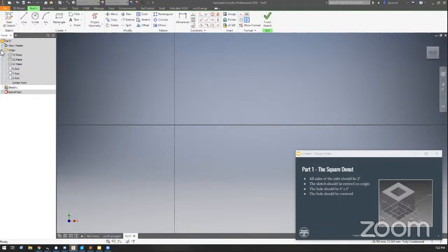It's not wrecked. What you can do is use this project geometry tool and expand out in your viewer on the side here and see all the different planes. As I rub my mouse across them, you can see all the different directions of the planes. Once you've selected geometry, click on center point. And once you've done that, you've brought that reference point back into your sketch. You're still in this project geometry mode because your cursor has an arrow and a plus sign, so hit escape to get out of it.